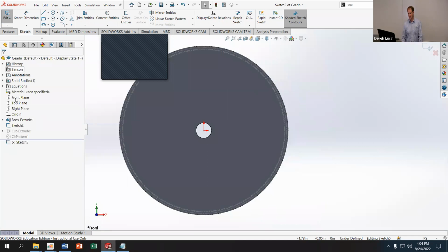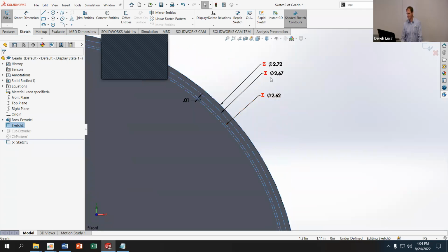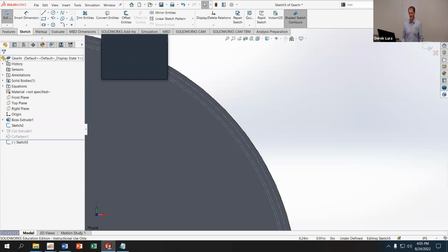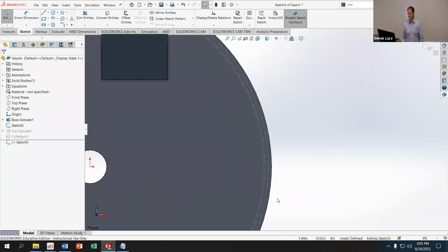I'm actually going to exit this real quick. And I want to use this size right here. That is sketch 2, but the size for that is this one. So you can see that on mine, it is D2 at sketch 2, but go into yours and make sure that yours is whatever it is. It won't let you use diameter in the equation-driven spline. I tried it. I don't know why it doesn't work. I looked on YouTube to see if I was doing something wrong, and they said the same thing, that it doesn't work and you need to use the dimension.